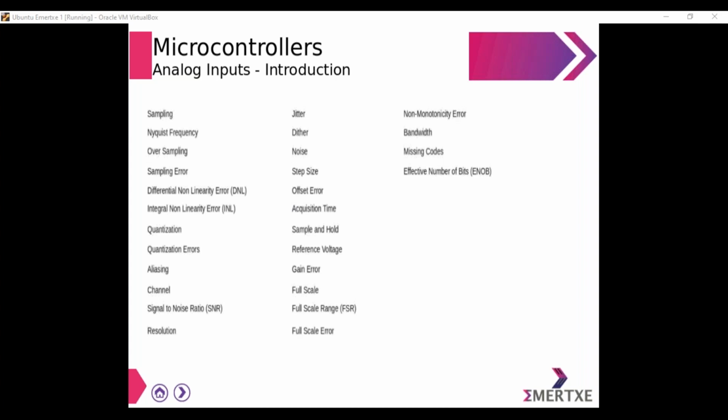So to start with, with respect to the PIC16F877A microcontroller, as I said, if ADC is not available, you may have to connect it externally at a particular pin of the microcontroller. But if ADC is available, we are going to configure the same ADC. Our microcontroller has a built-in ADC, so we are going to configure that particular ADC. Okay, so let us start.